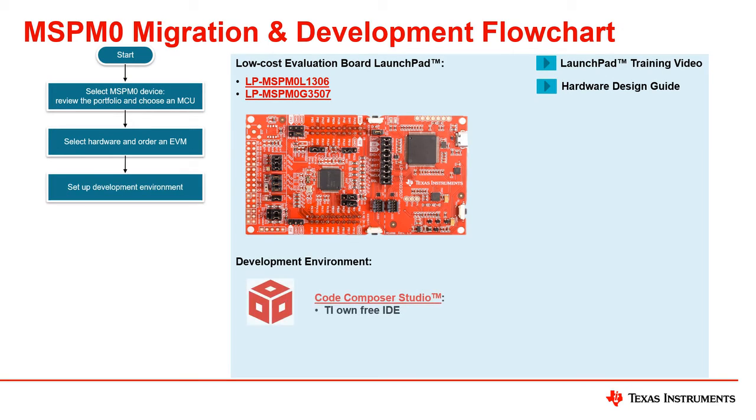The third step is to set up the MCU development environment. Most customers will start using Texas Instruments' own free IDE, CCS, but you can also use IAR or Keil. Make sure to download the MSPM0 SDK as part of your IDE installation. Please click on the IDE training video link to view the training content for the MSPM0 IDE.